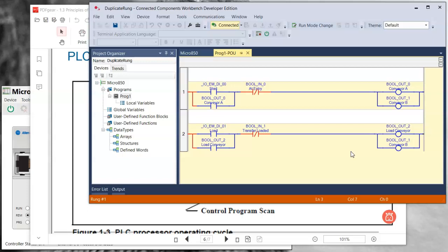So it's a little bit of an unintended consequence when I drew this up, but what happened here is a great lesson. Most of you did what I have on the screen here, where rung 1 was the start switch going through the conditional of whether the photo eye at the transfer entry was activated or not, and then that would turn on both conveyor A and conveyor B. When we latch it in on itself, we could pick either A or B, or some people put A and B in series with each other.